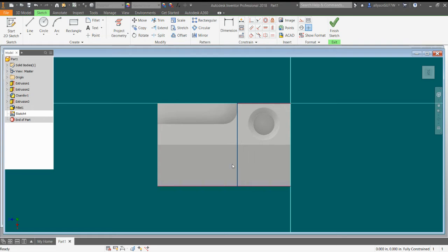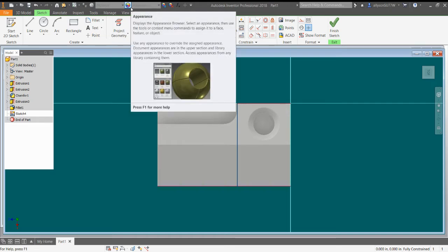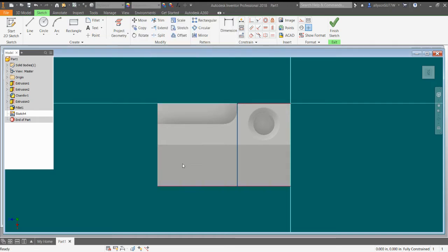The next thing we're going to do is draw a tombstone where this line is the center of the tombstone. And it also gives us dimensions. So this tombstone is going to be 0.63 inches tall, and it's going to have an arc that has a radius of 0.5. So let's come into our line tool. We are going to start with our line at the bottom.